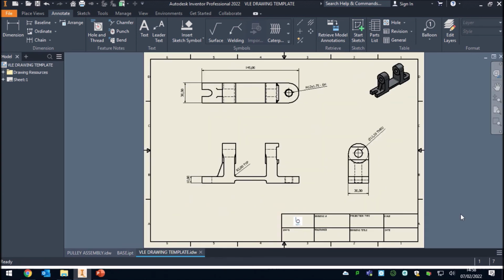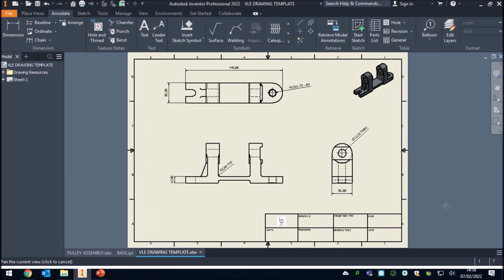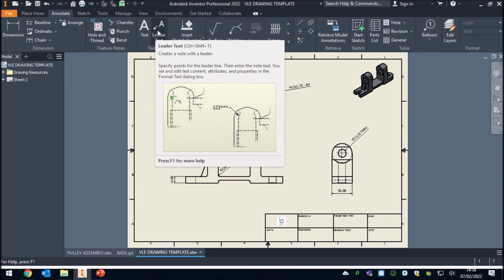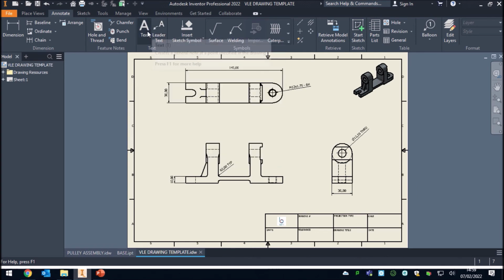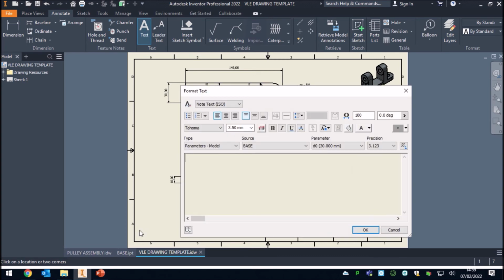Alright, so there's loads of new dimensions that need to be put onto that, but I'm going to leave that for now, and then obviously you can practice on your own job. One last little bit I'm going to show you is how to put a bit of text onto the page, because it may be you need to add a little note. So if I click on the text here, and then you'll see a little yellow dot. If I left click on that, always capitals, remember. Dimensions, and obviously you can type whatever you want into this box.